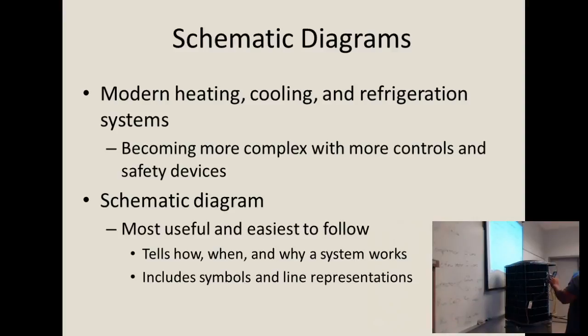All right, now the last thing. Back off. Just no, I mean that way. I got some wires here that say 24 volts from my T-stat. In other words, the T-stat, somebody went by, put it in cooling and said, I need air conditioning. So one of them is 24 hot, one of them is 24 common, and they go to the sides of the coil. Go ahead. Contactor, go to the sides.